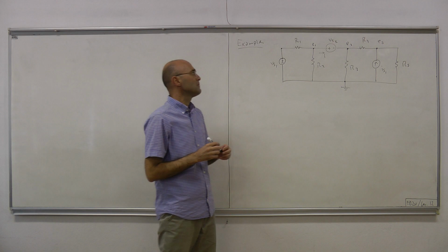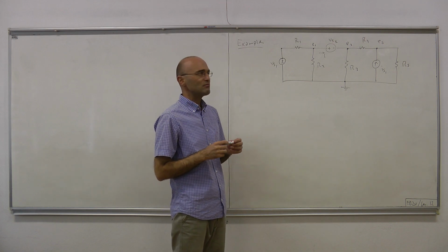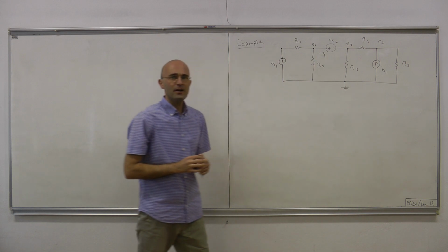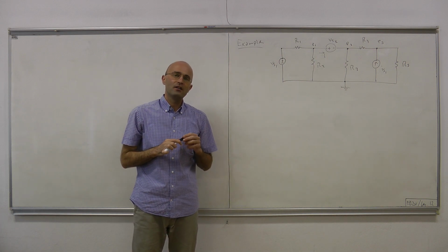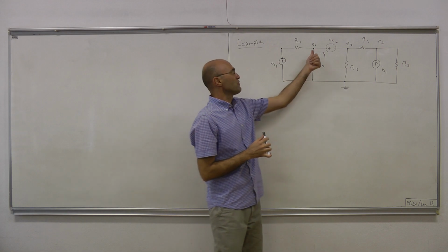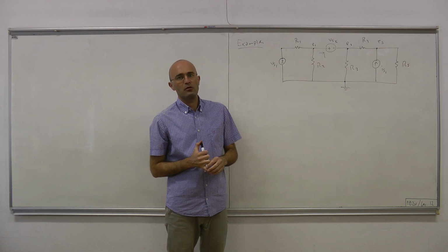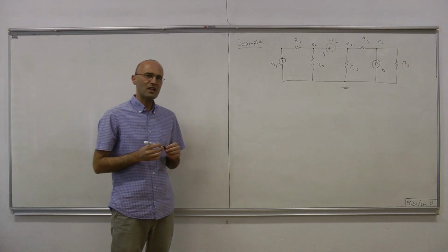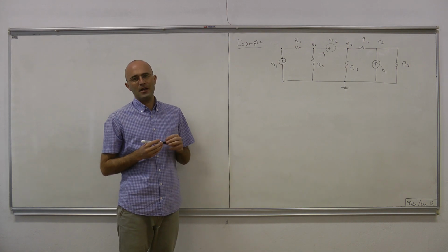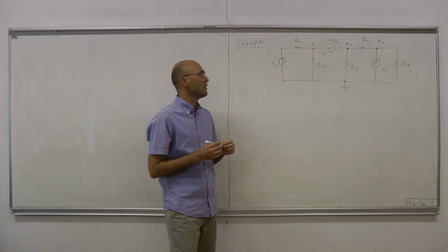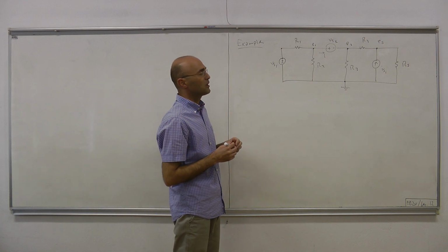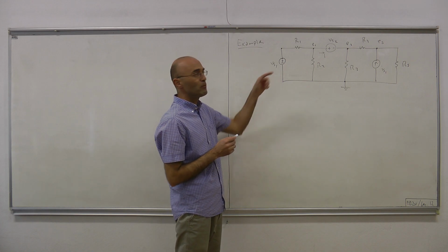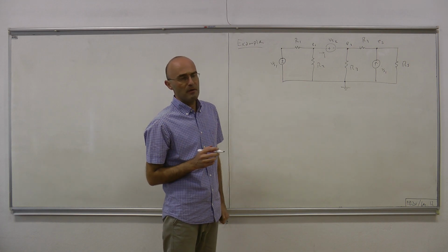Today, we will improve that method and get rid of that I altogether and see how we can formulate the circuit with 3 formulation variables, E1, E2, and E3. And then we will move on to the dual method, namely the mesh current analysis method, in which we will formulate the circuit in terms of mesh currents. But now let's talk about the modification of method 1.